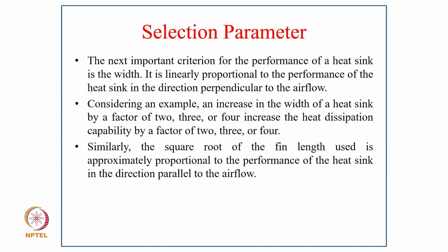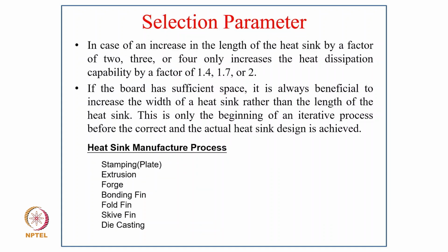Similarly, the square root of the fin length used is approximately proportional to the performance of the heat sink in the direction parallel to the airflow. So an increase in the length of the heat sink by a factor of 2, 3 or 4 only increases the heat dissipation capability by a factor of 1.4, 1.7 or 2.